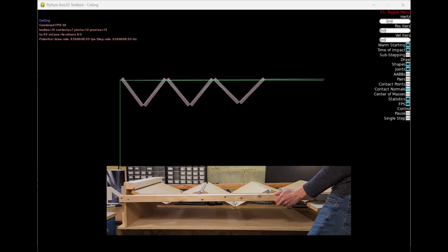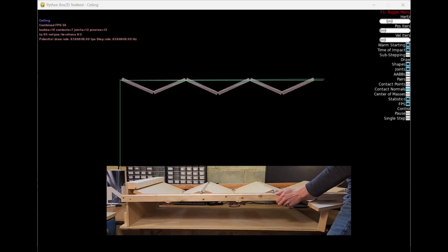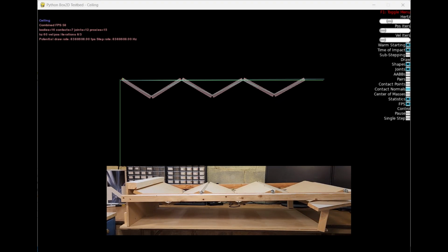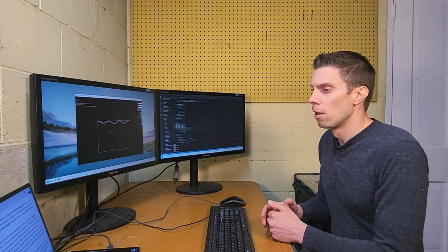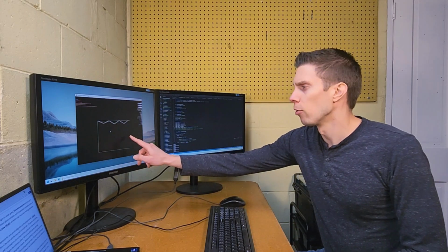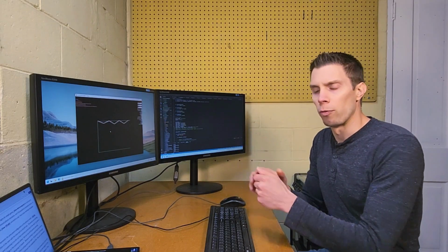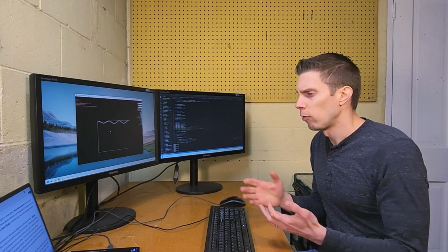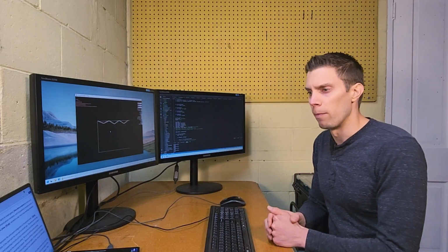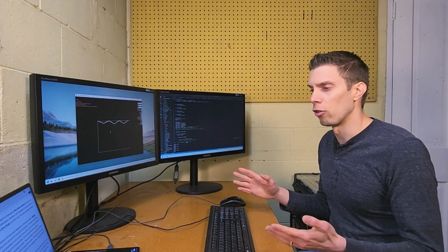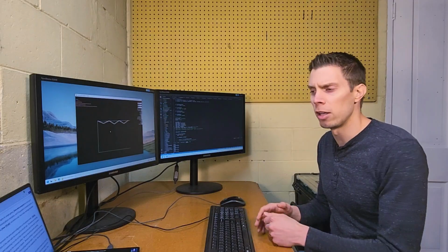We can see all the panels opening together in that accordion shape, and then this is what I knew was going to happen. Because nothing is supporting the bottom of the panels, the only thing that's causing them to flatten out is that horizontal force pulling the pair apart. 50 pounds is not enough to flatten them completely, but in fact, I could increase it to 500 pounds and it still wouldn't be completely flat.